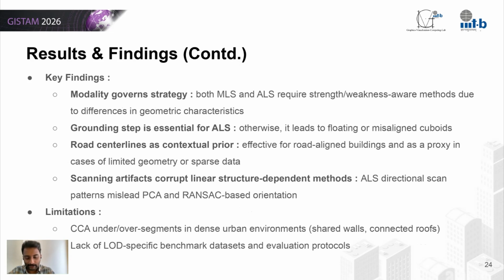Sharing our key findings. So we have implemented 5 LOD 1.0 reconstruction techniques, and our findings show that the reconstruction strategies are strongly influenced by the LiDAR modality, and ground alignment is essential for ALS. Without it, the reconstruction fails miserably. Road-based priors are useful but not universally reliable. We also observe challenges such as segmentation errors, scanning artifacts, and lack of standardized evaluation metrics for LOD 1.0.